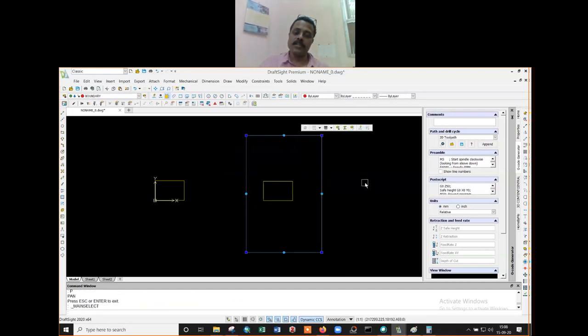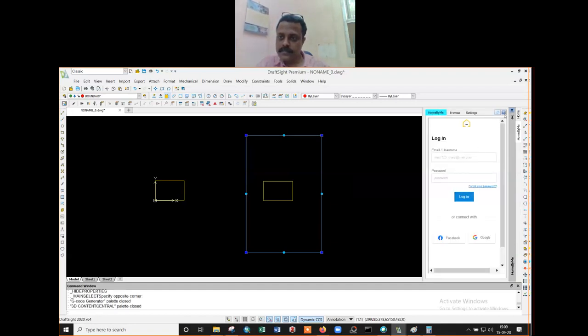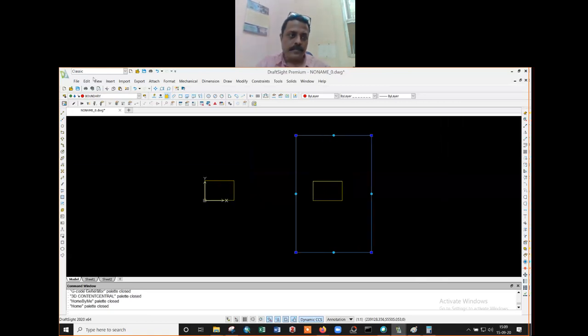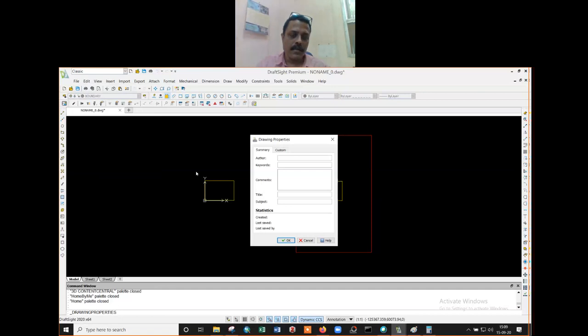So in order to change the scale, you pick this line type or the boundary layer and then press, what? Or you just wait a minute. In AutoCAD, you can press Control 1 here. You can go to Edit, File, Property.